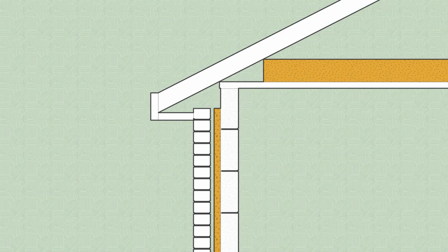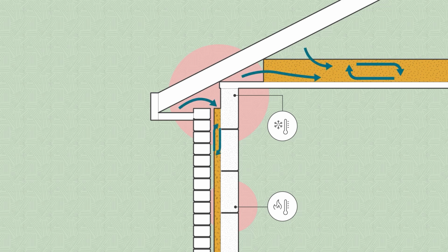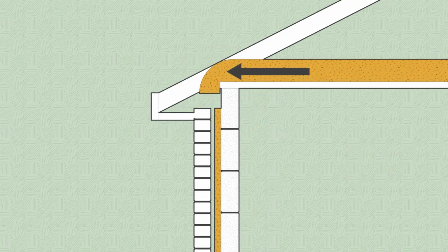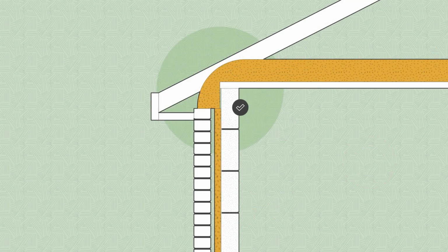The way that you install insulation also matters. Gaps between insulation materials and other elements can create thermal bridges. These gaps can also cause thermal bypass, where outside air gets between insulation layers or goes around the insulation altogether. These quality issues greatly reduce the efficiency of insulation and can cause damaging condensation and mould, so take care to ensure that insulation is properly installed and gaps are mitigated.